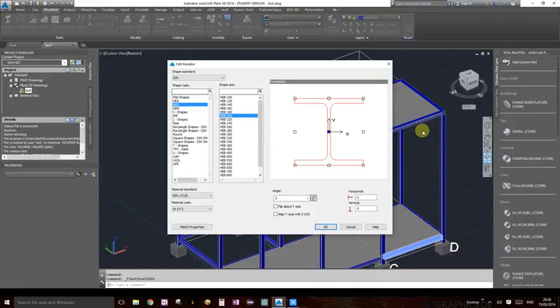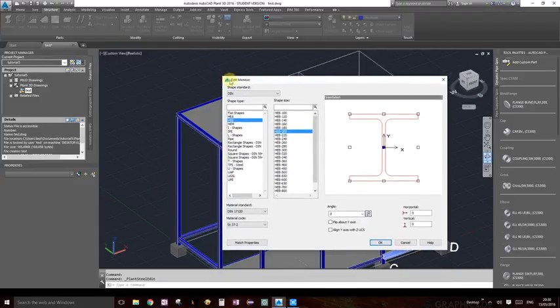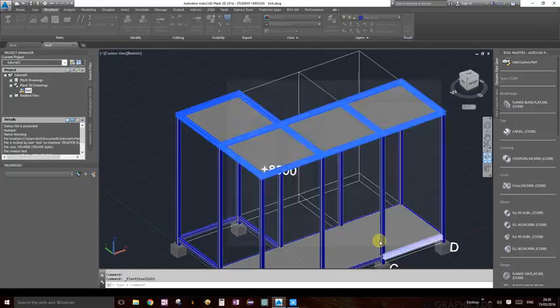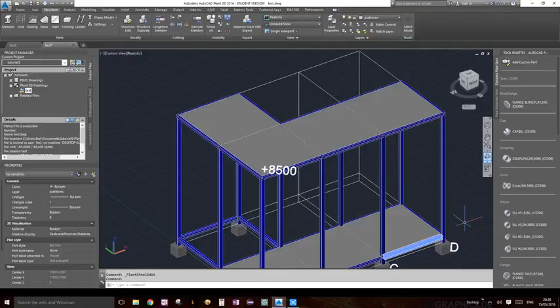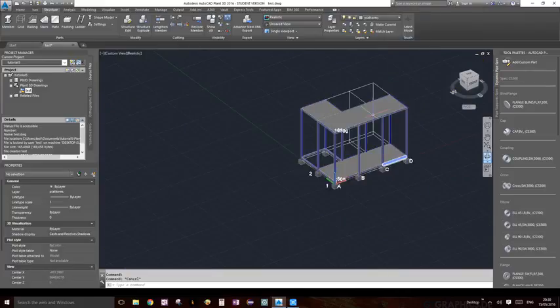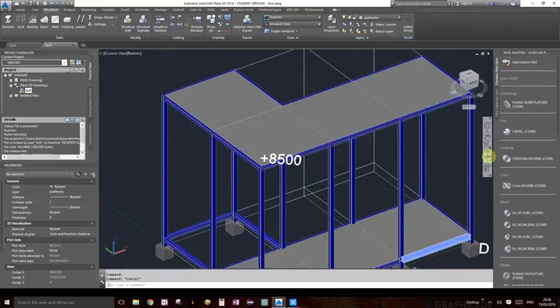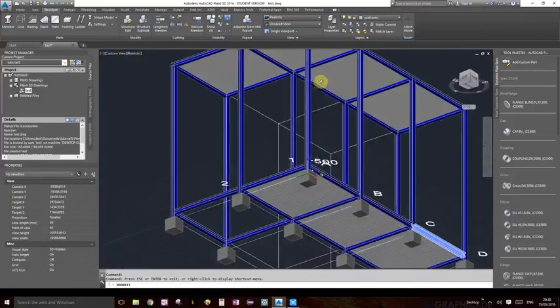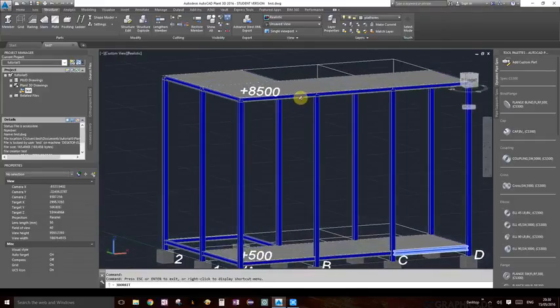What I've done there is select all the upper horizontal members and click on structure edit, and I'm going to say orientation is top justified, everything else is the same, and bam, it's done. Now our grading has moved to the proper spot. Now you can't see them through it, because obviously in real life you won't be able to see through that.